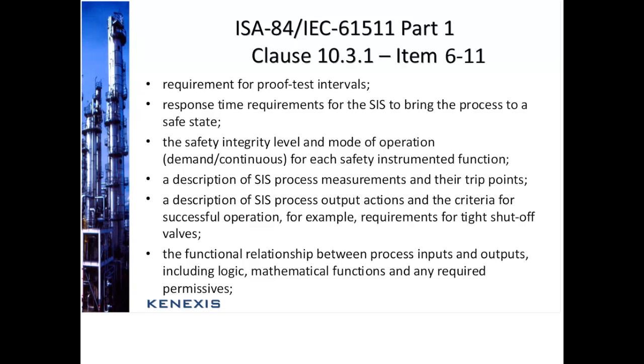Possibly it's a fuel gas system and some NFPA requirements say that the gas valves must go from the full open to the full closed position within a 1 second period of time. That would be the response requirement.